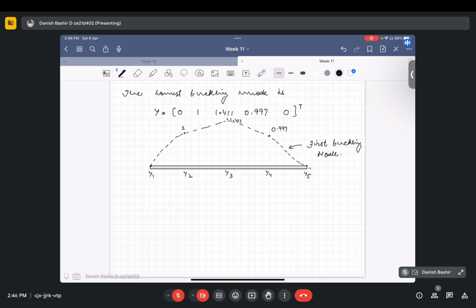So we had shape functions for lower order elements where we assumed a linear trial solution for our element solution between the two nodes. We can have a quadratic solution between the two nodes. Okay, we can assume that one, and then we can deduce the shape functions.